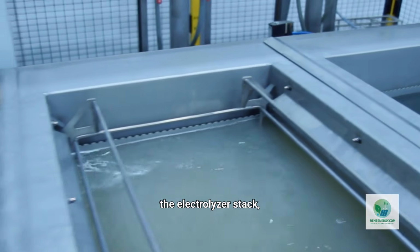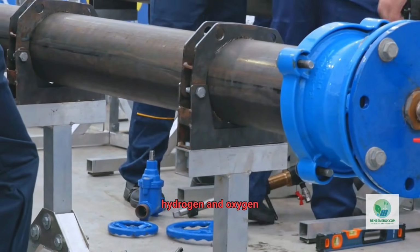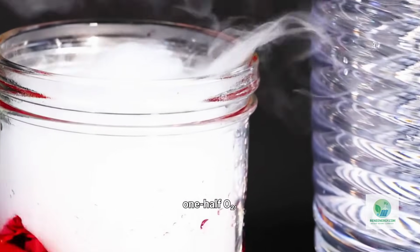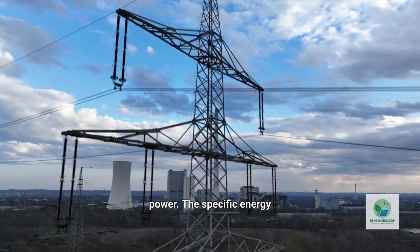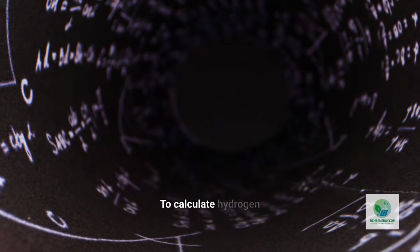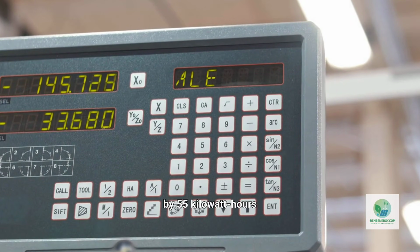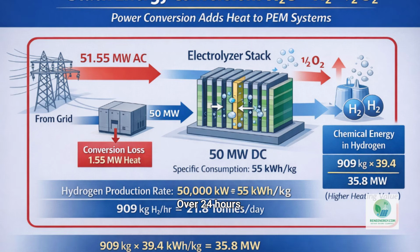Inside the electrolyzer stack, the electrochemical reaction splits water into hydrogen and oxygen. According to the reaction, H2O produces H2 plus 1/2 O2. The stack consumes 50 megawatts of direct current power. The specific energy consumption at the stack level is 55 kilowatt hours per kilogram of hydrogen. To calculate hydrogen production rate, we divide 50,000 kilowatts by 55 kilowatt hours per kilogram. The result is 909 kilograms of hydrogen per hour. Over 24 hours, this equals approximately 21.8 tons per day.